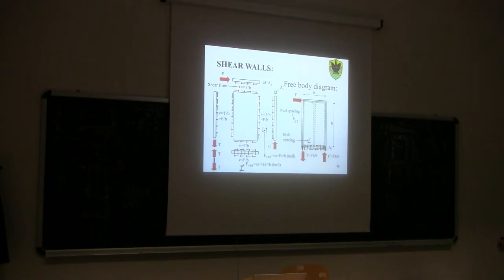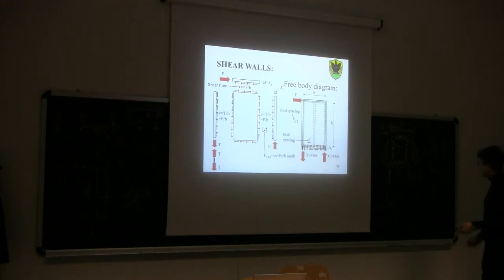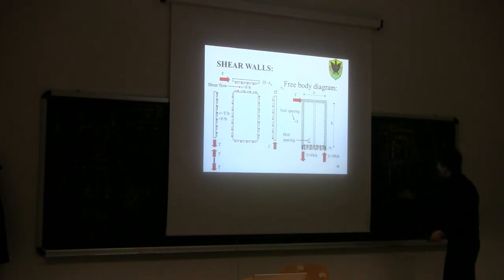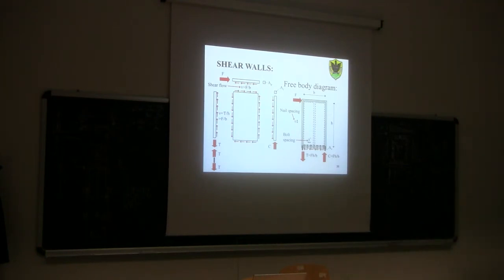No, we use the same symbol, okay. Then you will find the same symbol, FVD, to indicate the bolts. This will be V, the shear force, times S prime. So in the end, F over B times S prime. Because again, also here, we have always the same shear going around the sheathing panel. So basically, you can see all these forces here are constant.